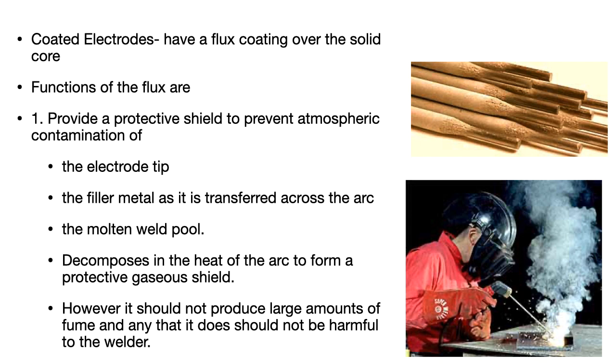Whenever we are welding, we normally keep a blower unit or a suction unit nearby so that the excess amount of fumes which are generated are sucked out of the area, and the welder is exposed to a bare minimum amount of fumes.